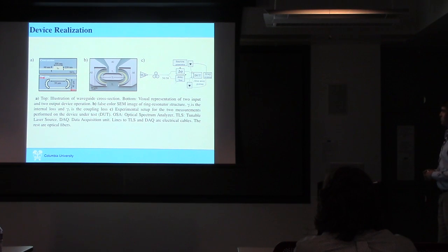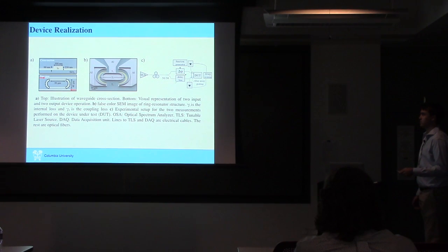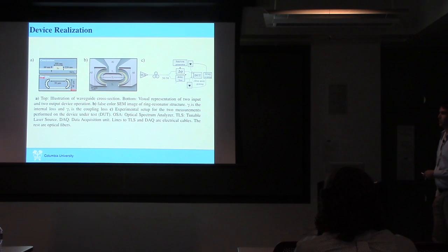This is our setup that we used to test this. The two waveguides coupled in, we actually coupled them in separately, and we used fibers to do an off-chip delay. So we use a lithium niobate phase modulator to impart a delta phi compared to the other, and then we have a delay line, which we got pretty far into interferometry today, but it's basically just to make sure we see the fringes.